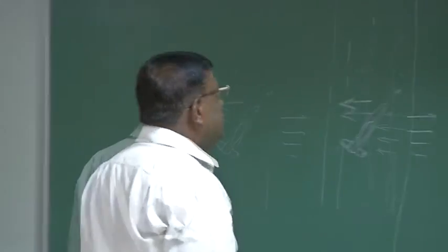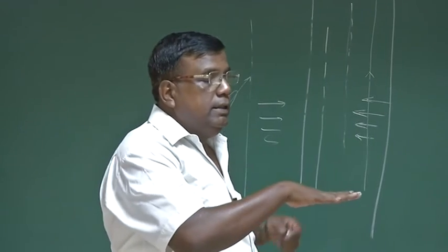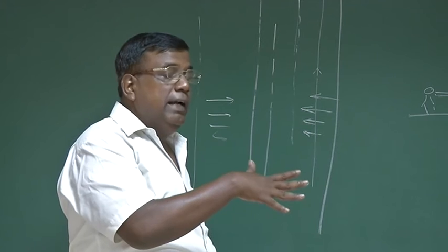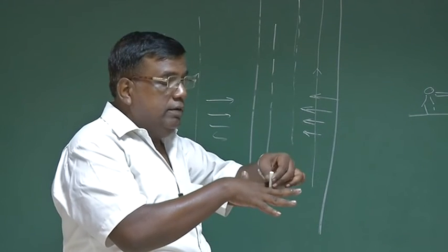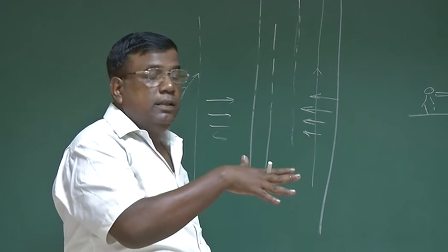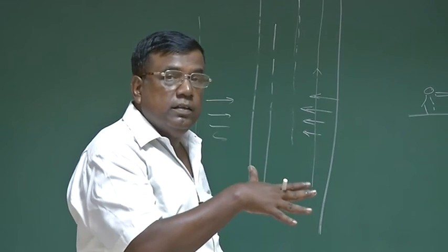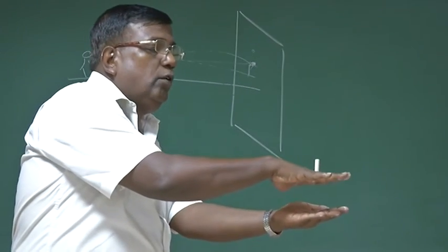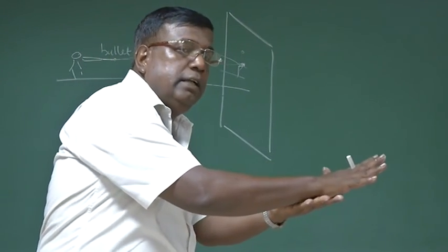Right? This is one way. The second way is I am flying like this and the wind is coming from my right. So I'll be drifted like this. What I do, I bank my airplane. And once I bank it, the lift vector is like this. One component of lift will try to resist this drift. And I go like this, and near the airstrip, I roll back, flare up, and touch down.